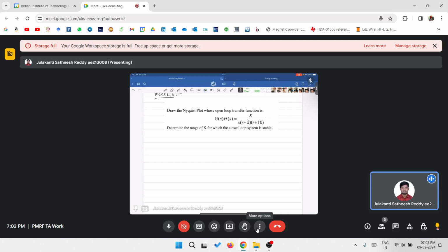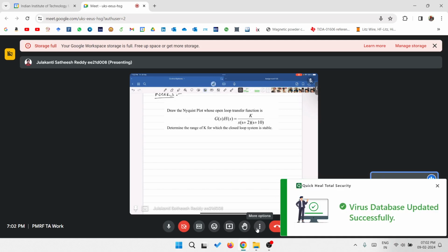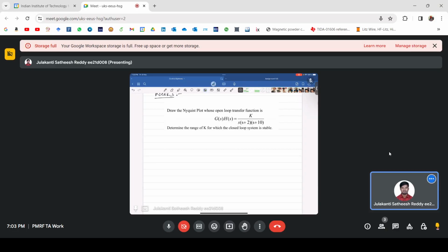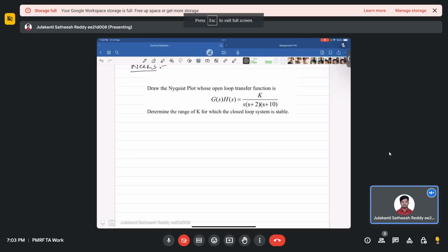So we are talking about the S plane. S plane is all about sigma plus j omega. Sigma indicates the gain, you can say the real component, and omega indicates the frequency component. We are not considering any sigma here, because we are interested only in understanding the stability criteria by knowing the j omega axis. So we are only considering the boundary line as j omega.